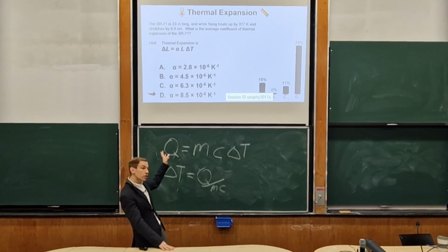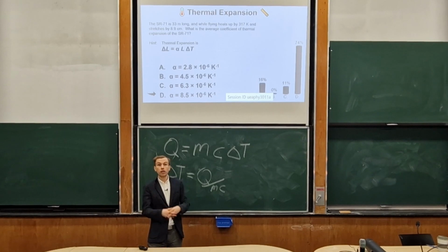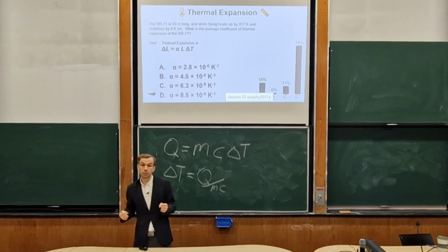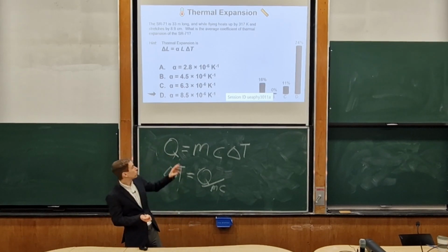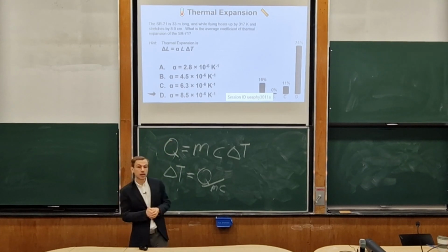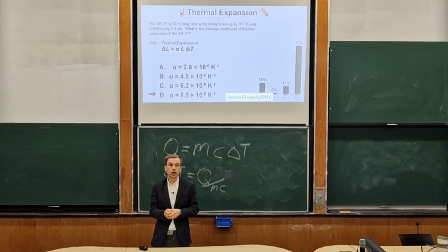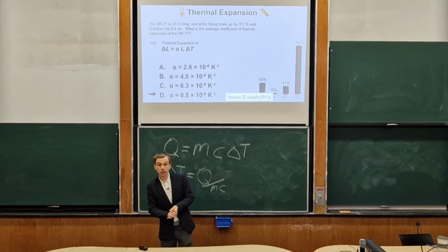So this is actually the thermal coefficient of expansion of titanium, which is what the aircraft is made out of. The aircraft is basically titanium. So that's what's going to determine how much the aircraft is going to expand by. One last thing to say about this. If we look at how much the aircraft is going to increase in temperature by, that really does determine the kind of materials that we can make the aircraft out of.